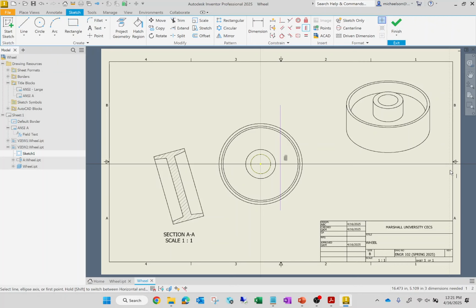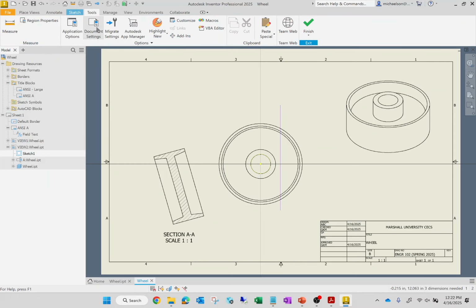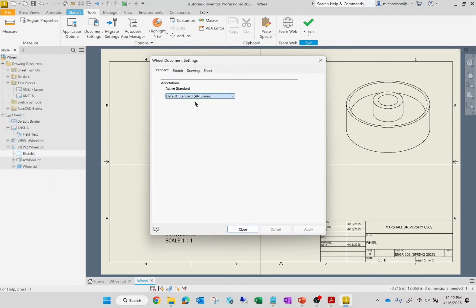Now what? Well, now I'm going to add a dimensional constraint. So I'm going to force the dimension of the line. And there's no real magic to this part, by the way. So I'm going to apply a constraint. Uh-oh. Wait a minute. Take a step back. Why does that say 5.112? Because I didn't change the units. This is a very easy thing that's going to happen to you maybe in assembly land. Maybe it will, maybe it won't. How do you fix that? You go to Tools, you go to Document Settings, change the units.